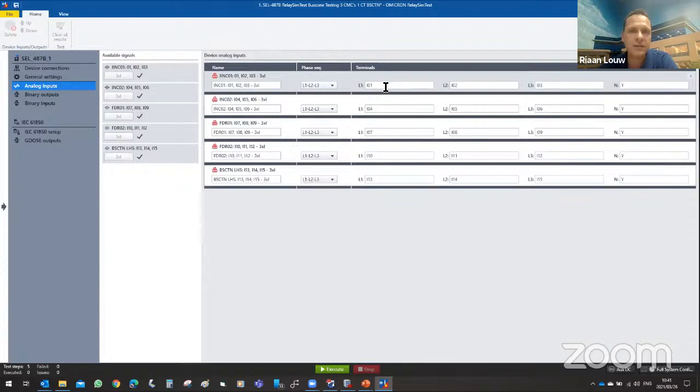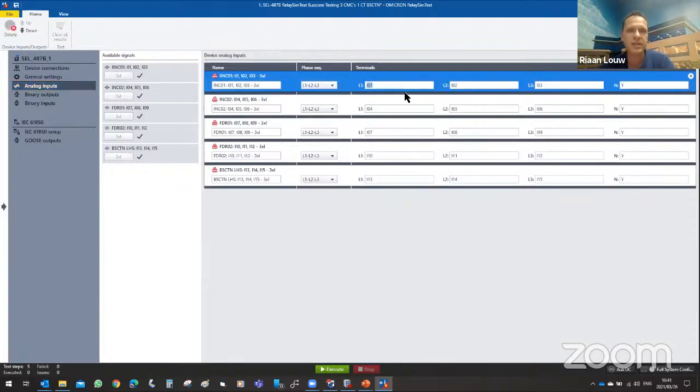And I've just given them the unique names as they are associated to the relay terminals at the back. So this is IO1, IO2, IO3, going all the way through the sequence up to IO15. Now, had I used a system with a second CT on the bus section, I would have continued here with I16, I17, and I18, and I would also simulate that CT then. Not the case for today, but just worth mentioning.